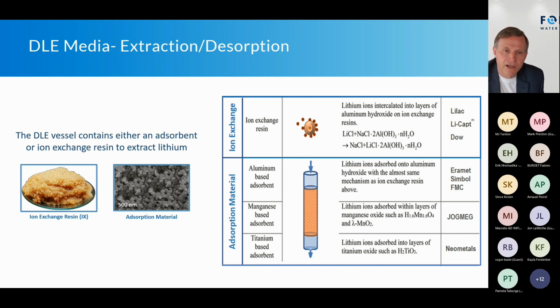If you take a look at the ion exchange material and the absorption material, sometimes it's very difficult, or you cannot tell the differences between the two unless someone tells you. Resins are very, very small. This is at 500 nanometers here. So kind of indistinguishable. So make sure you label the resins and absorption materials if you're doing testing, or you could mix them up very easily.